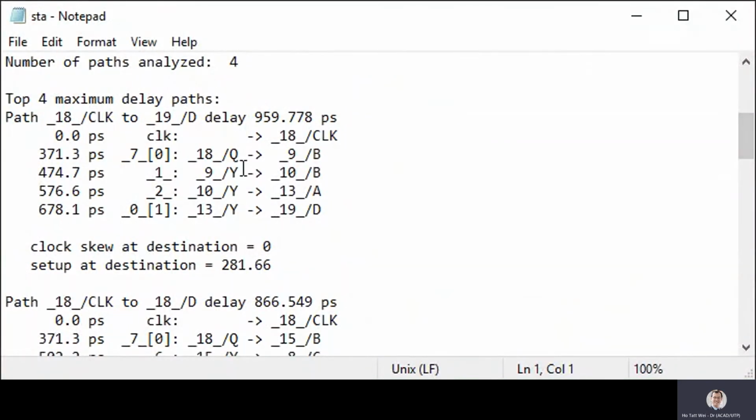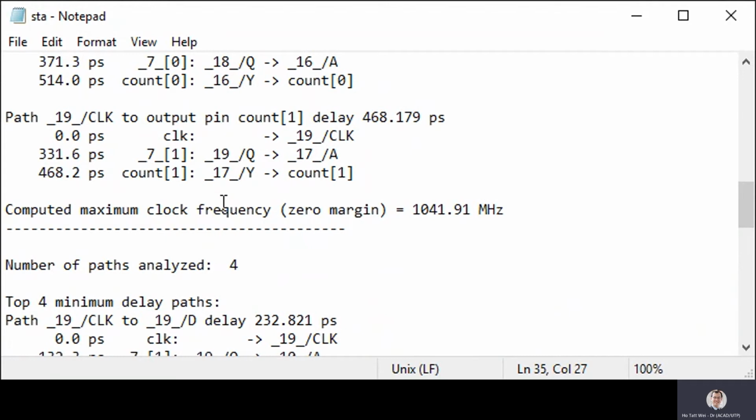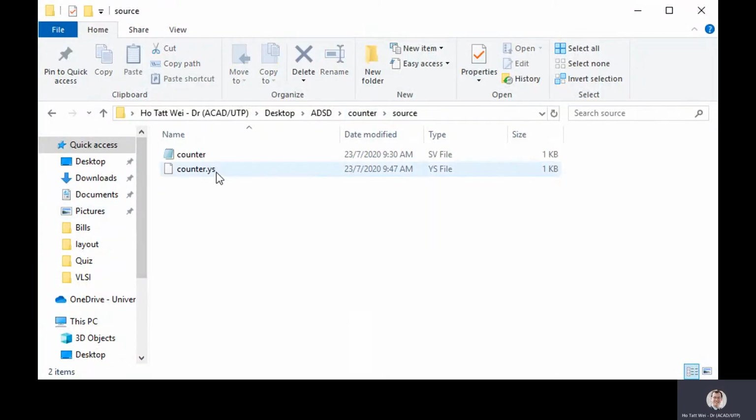The STA log file would report the max delay and mean delay and clock skew and pin-to-pin delays that are achievable by your design. Okay, so this is interesting that some of these log files actually have useful analytical numbers in them. But viewing the log dumps is one way to visualize this, but there are also other ways which I'll point out shortly.